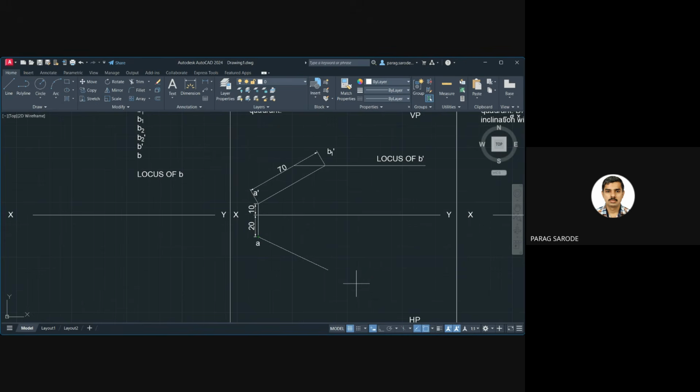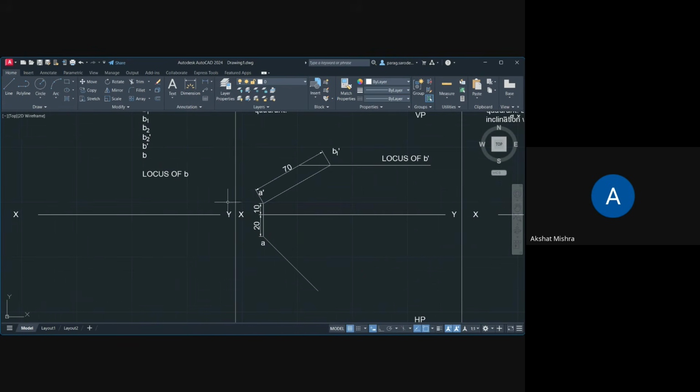Now there is a question here. You can see 334 degrees. That appears whenever we measure the angle counterclockwise, which otherwise would lead to 315 degrees in the 360-degree full circle, and 45 is what we want. So what we can do is press minus 45 like this, so automatically this angle will be 45.